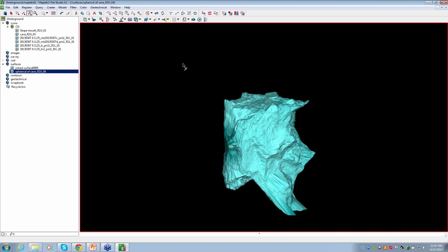That is not the limit of the scanner. That was actually programmed in to make it a little bit faster to run it through the process and get it calibrated. So at 200 meters, you will see just as much data as you will at 100 meters. That is not the limit of the capability of the scanner. We actually programmed that in there. So 200 meters is fully usable data, and it is 8mm accuracy.